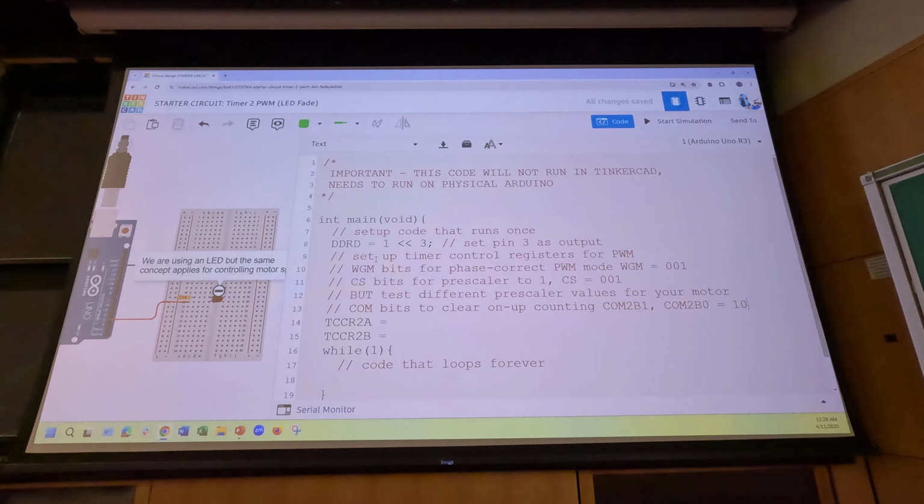Okay, so think of these just like all the little control switches or settings we need to turn on to be able to enable PWM mode. Once you've gotten that headache out of the way, you only need to do it once at the beginning, and then there's just a single register we're going to need to change later to change the speed or the duty cycle of the PWM signal. Okay? And again, I jotted those comments down there. If you have a better way of writing this down such that it makes sense to you, you can write whatever you want for the comments.